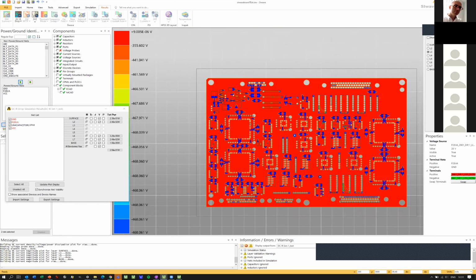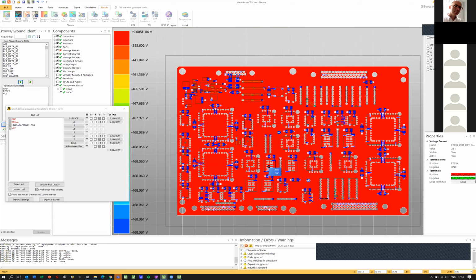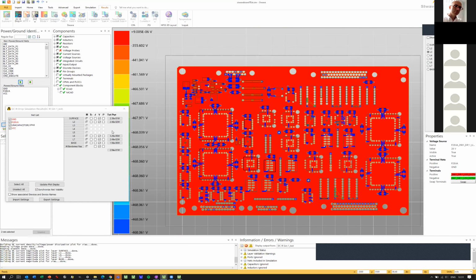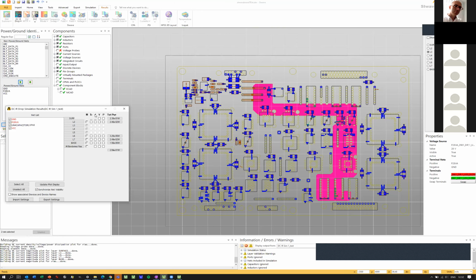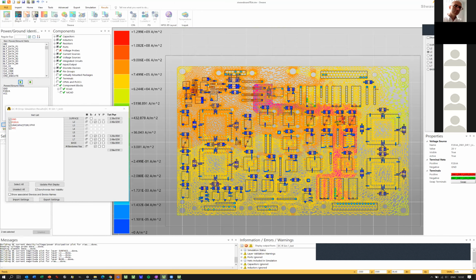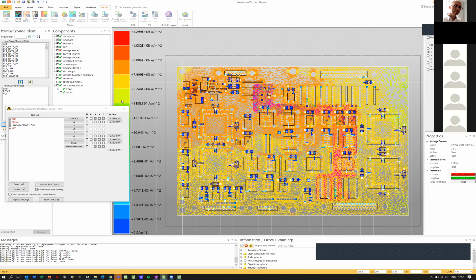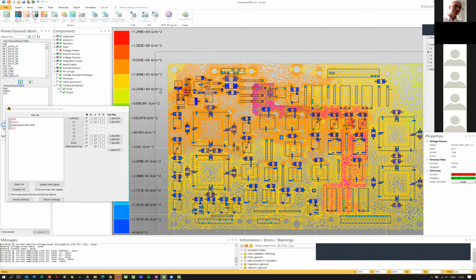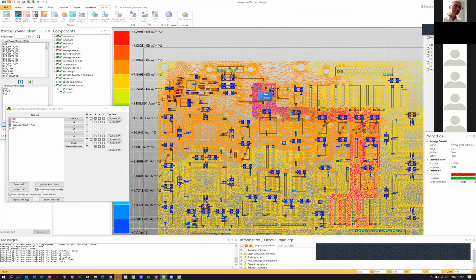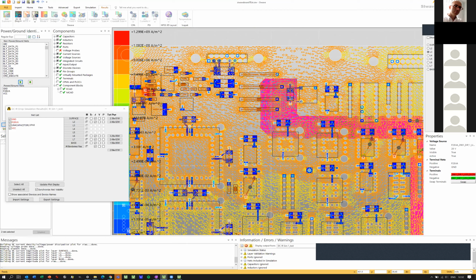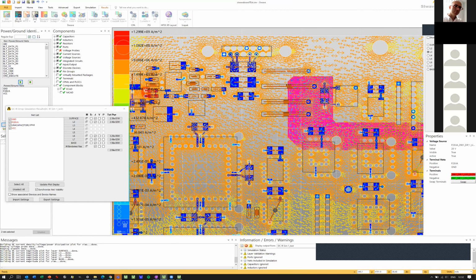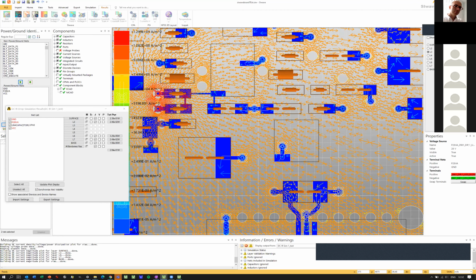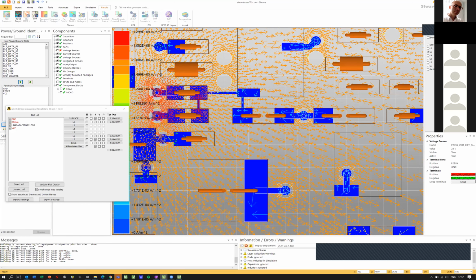And this is the voltage distribution. Oh, this looks nice. So we have a good distribution of the voltage. So this is not a problem on this circuit board, but this looks a bit more interesting. This is now only showing the surface current density. So once again, we can see that a lot of things happen on these two vias. Now it's the question how much these components can survive, how much these vias can survive current.